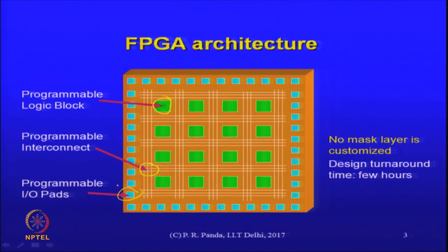So, here programmability, we are not referring to the software settings which we do. Here we are referring to the logic connection. Yes, the logic is being programmed, meaning that now it can do some piece of logic, but in a reprogrammable architecture, which is what these modern FPGAs are, you could change that function to something else. The hardware function is being changed to something else, as opposed to a processor in which the hardware is not changing.